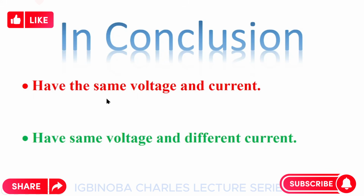Before connecting panels in parallel, ensure that all the voltages of the individual panels are the same. Otherwise, if any one is different in the entire system, it is the panel with the smaller voltage that is used in the calculation, and this will result in a large power loss in the entire system.